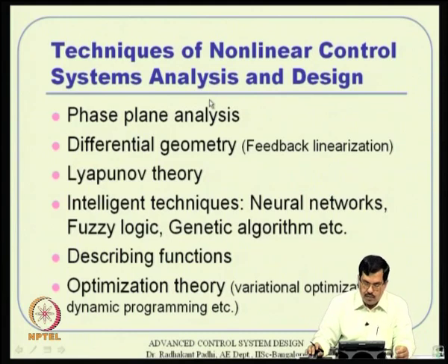When you talk about nonlinear systems analysis and design, there are a variety of ways that you can do that. There are a lot of techniques. First is phase plane analysis. This is valid for small systems like second order systems and things like that. It can be extended mostly up to third order, but beyond that graphical interpretation is difficult, and hence we do not use that. And then there are differential geometry based concepts. Some of that we have seen already, that is feedback linearization or the dynamic inversion concept.